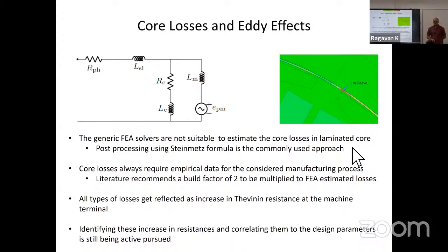Any questions? Why can't the sleeve be something else? It's costly. Mild steel is the cheapest. One application where this kind of sleeve is used is the engine starting motor. It should cost less than 2,000 or something. In very high speed applications where it is sensitive, they'll go for carbon fiber.